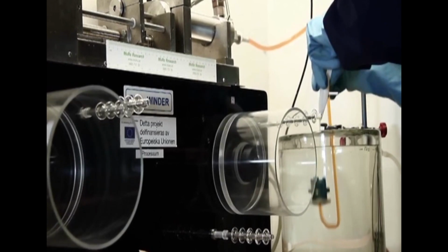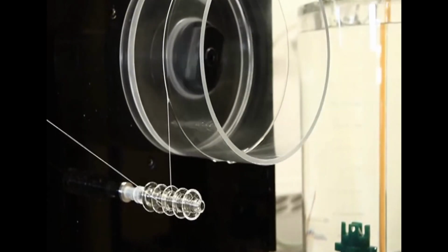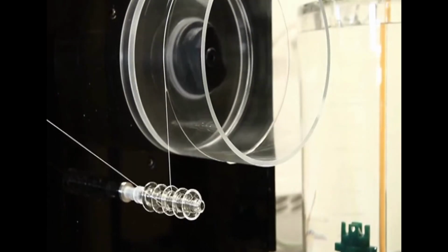And for this reason, we need spinnerets of high quality and which are corrosion resistant, because the spinneret has to be placed in a chemical bath, so that it is able to pass the polymer liquid through its holes into the chemical bath. So, in order to resist that chemical, the spinneret has to be made of some precious metal, which again requires huge investment on the part of the manufacturer. And so, in this process again, the non-volatile solvent is used to make the polymer into liquid form.